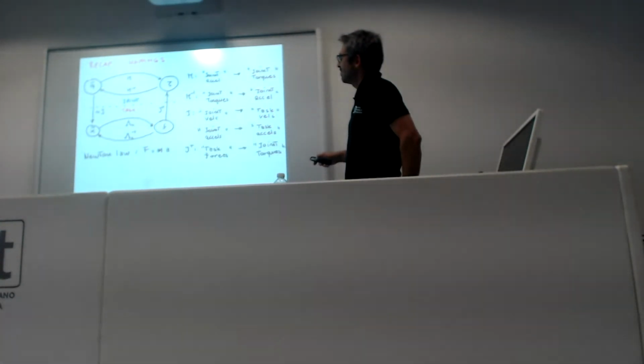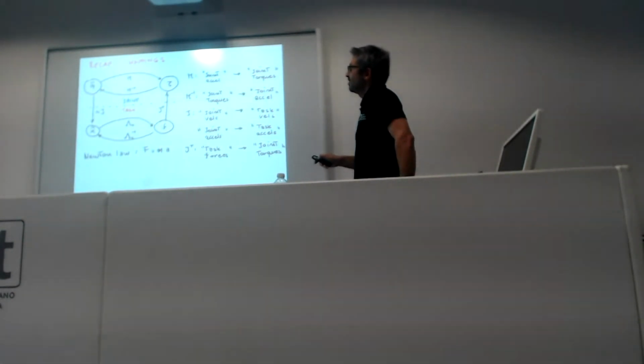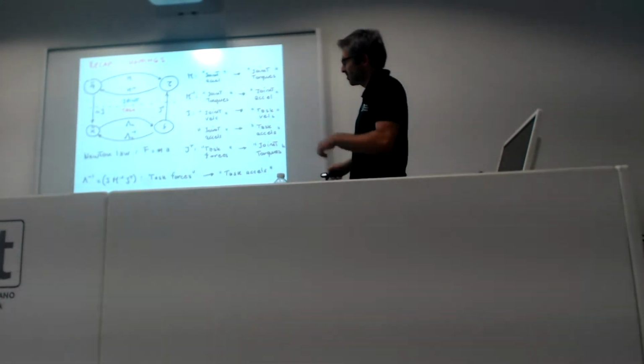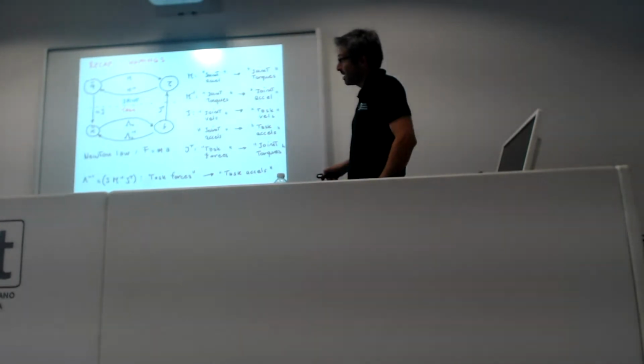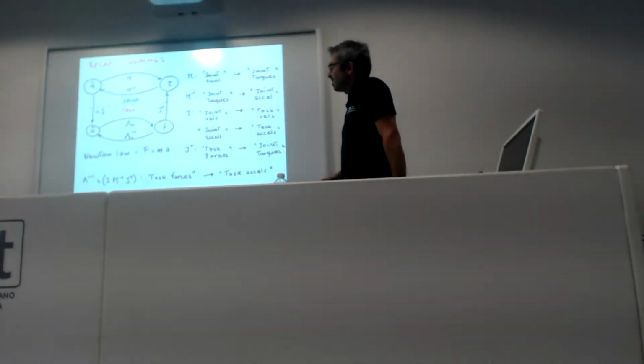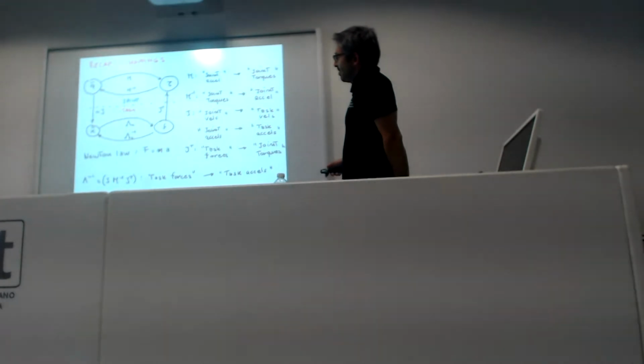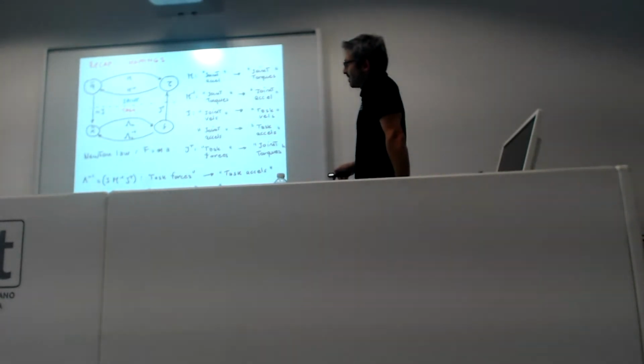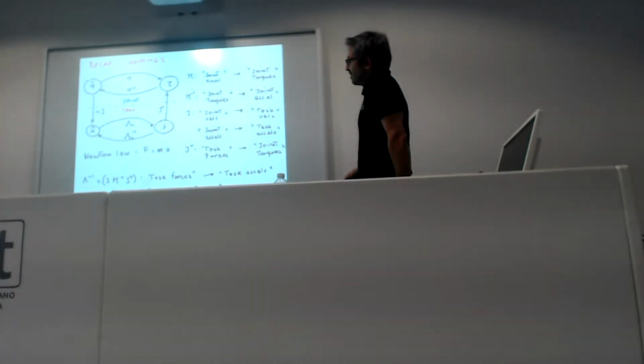And the Jacobian transpose is the dual that maps task forces into joint torques. And finally, we have the operational space inertia matrix. In particular, its inverse maps Cartesian forces into Cartesian acceleration, while the inertia matrix itself maps task acceleration into task forces.